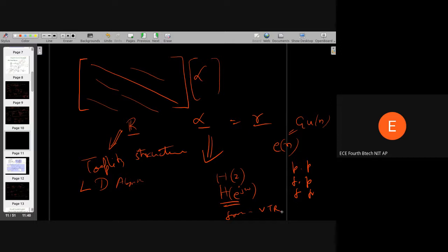On top of that, in Levinson Durbin's algorithm, in the process we have a parameter k_i, which are called PARCOR coefficients. The PARCOR coefficients are related to the reflection coefficients in waveguides, in the source filter theory vocal tract model, where the vocal tract system is a concatenation of tubes of different cross-sectional areas.